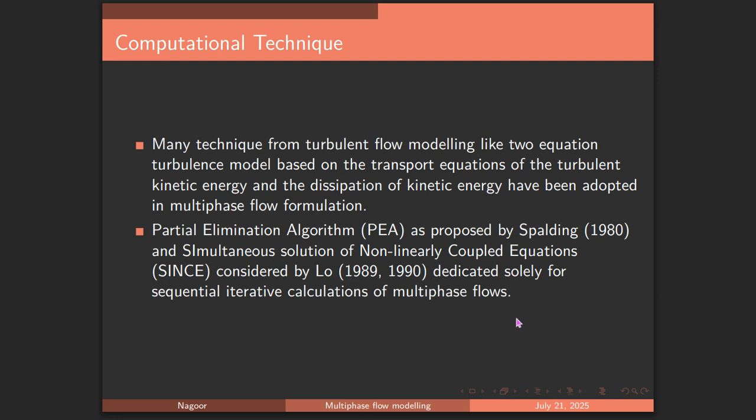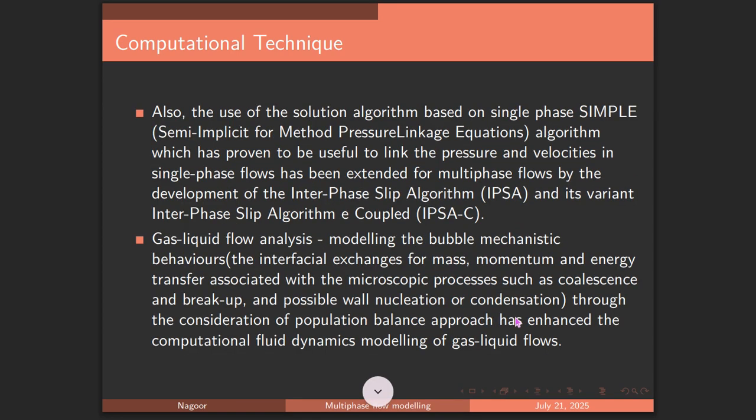And also, when we are solving with computational techniques, there are these interaction terms, nonlinear interactions, that have to be handled properly in order to get stable computational numerical solutions. Some of the numerical techniques that we adopted in single phase flows for handling the nonlinear terms, like the partial elimination algorithm or SIMPLE algorithms, are also tailored for the calculations of multiphase flows.